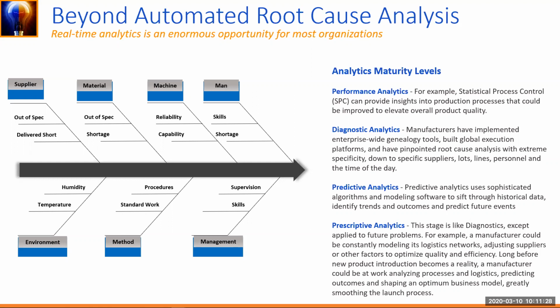But if I want to get into predictive, now what I want to do is track the actual process variables as that machine is performing its duties. An example here is at an automotive supplier right now, where we're looking at a grinding operation. Within that grinding operation, we can look at the power draw we're seeing for the motor that's driving the grinding wheel. As we see that power load increase in variability as well as in amplitude, we can start to identify when that grinding wheel needs to be changed.